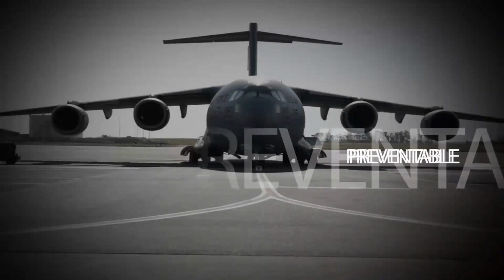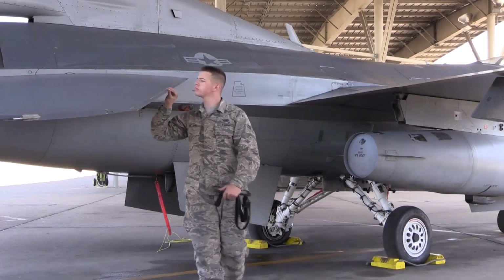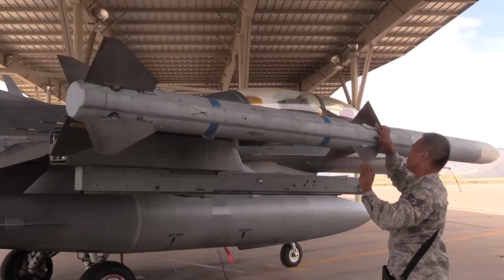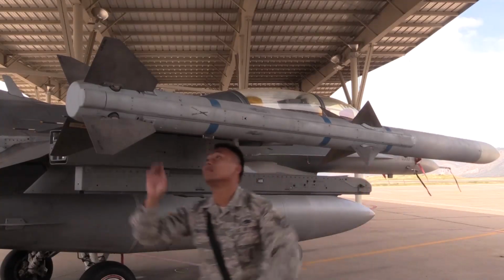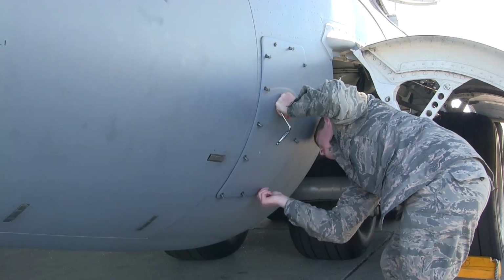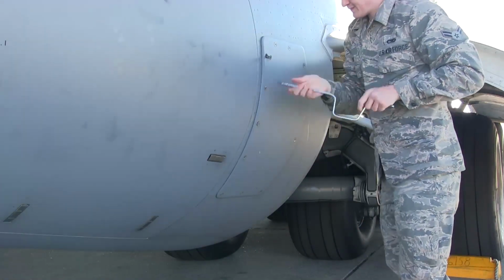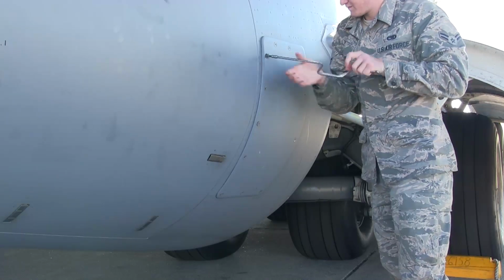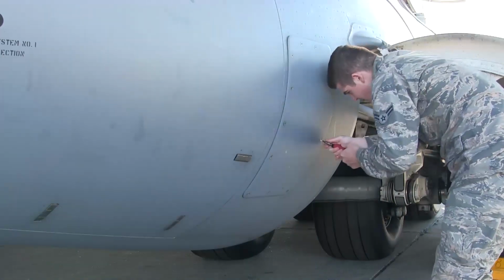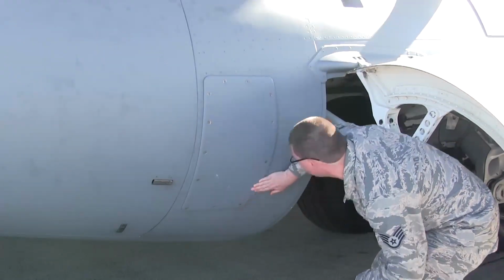Dropped objects can be prevented by performing proper maintenance, thorough pre- and post-flight inspections, weapons post-load inspections, and adhering to technical data. Following technical data can reduce known factors that have been attributed to dropped object incidents, such as loose, corroded, or improperly installed fasteners, such as bolts, screws, rivets, and cotter pins.